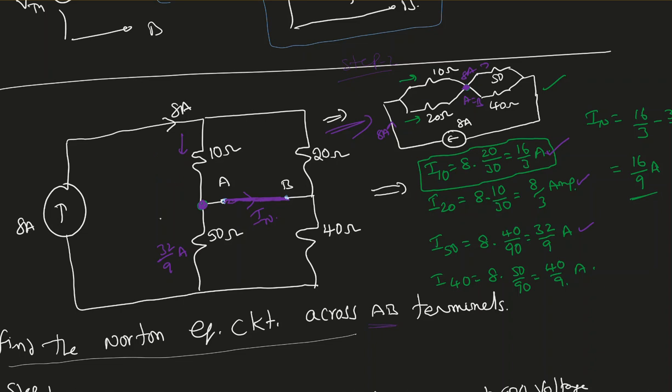Now 8 ampere current is coming from the source. Okay, so if I redraw the circuit diagram, it is like this: 10 ohms and 20 ohms. Now A, B are short circuited, so it is kind of the same voltage. In reality, say for example, this one has 10 volt. One of them will be like 9.9999 volt. That's how there will be some current passing through it. Otherwise, it could be 10 volt and this might be 9.9999 volts. So current can go through from B to A.